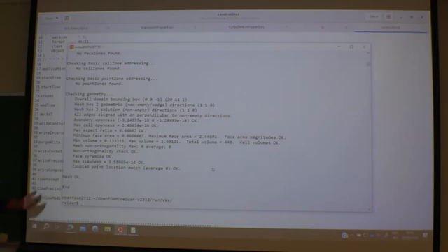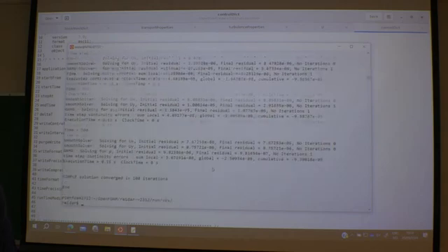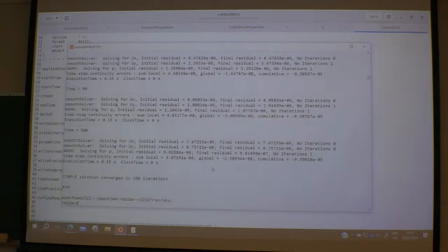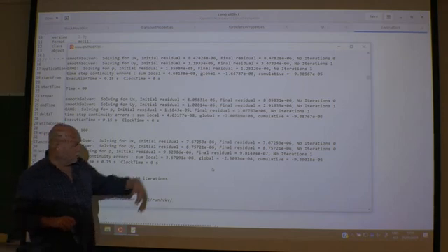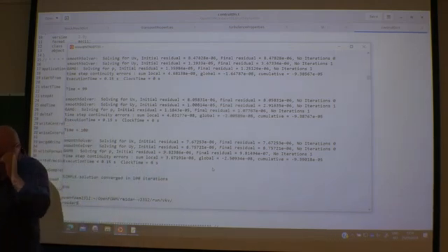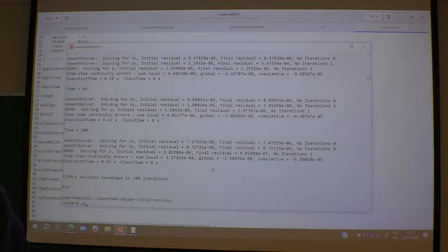And here, the mesh is going to be quite beautiful. Then we run it, should be quite fast. simpleFoam, and done. It used 100 iterations, solving for the velocity and the pressure, and the residuals are cute and small and very beautiful. So let's have a look.